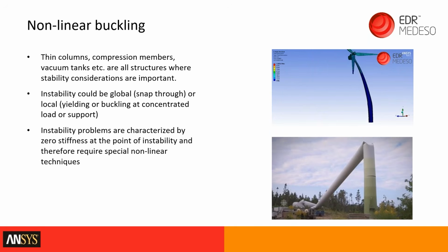So just to reiterate, nonlinear buckling problems are characterized by having, in the load displacement curve, a point where the stiffness becomes 0. And numerical methods really struggle when the stiffness becomes 0.